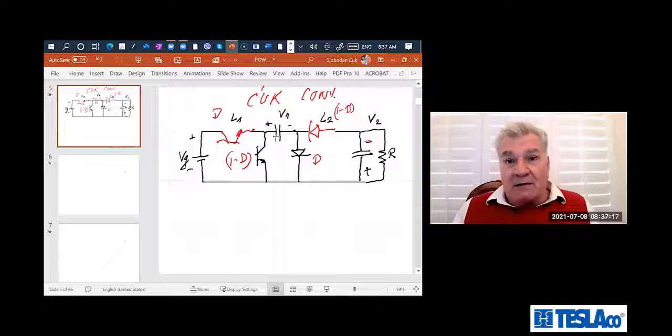I have only one capacitor, but that is a switched-capacitor converter, isn't it? And what's bad with it is that this capacitor goes against a DC voltage, which is fixed, and this has a ripple. Because you are trying to force this capacitor to eventually have the input voltage, the DC on it, and this capacitor on the output will be connected to the output capacitor, and there are different ripples, so you'll get losses with this. So therefore it's lossy.